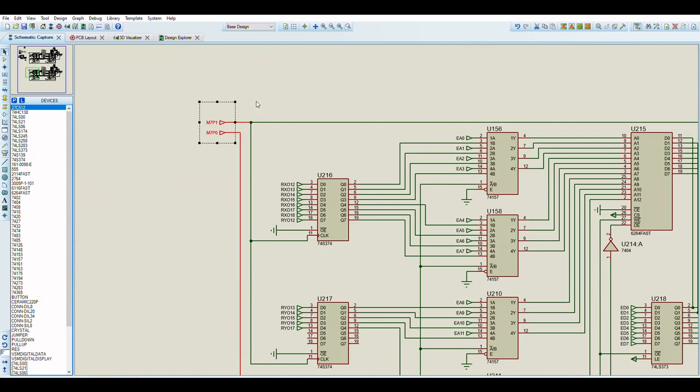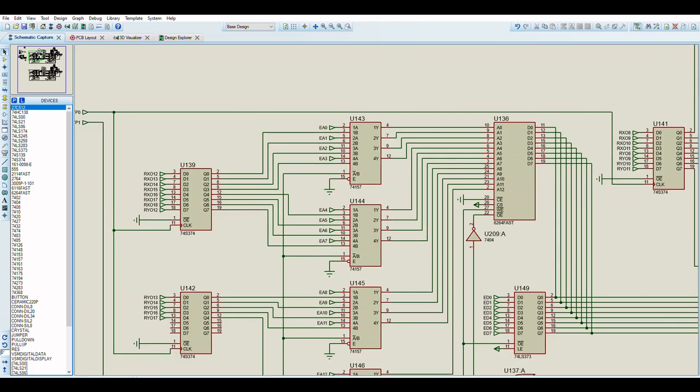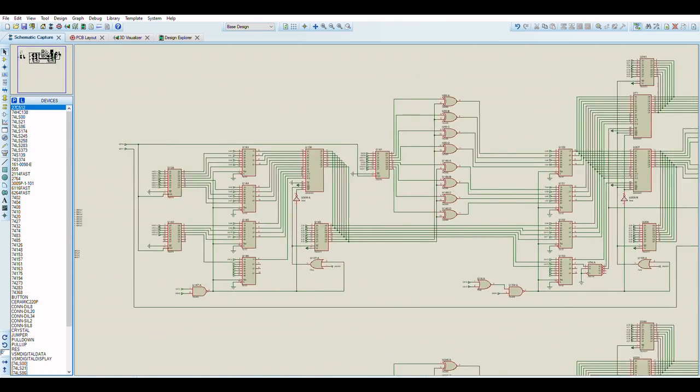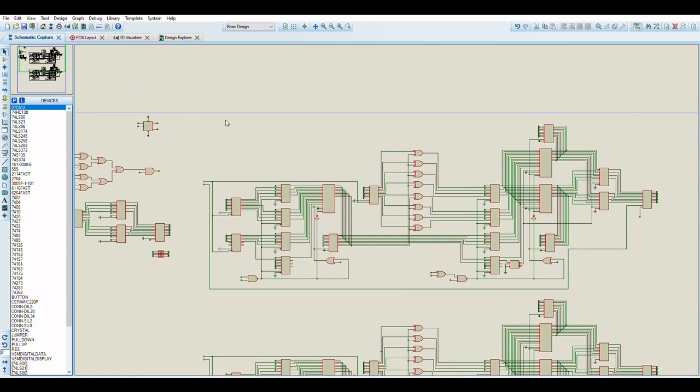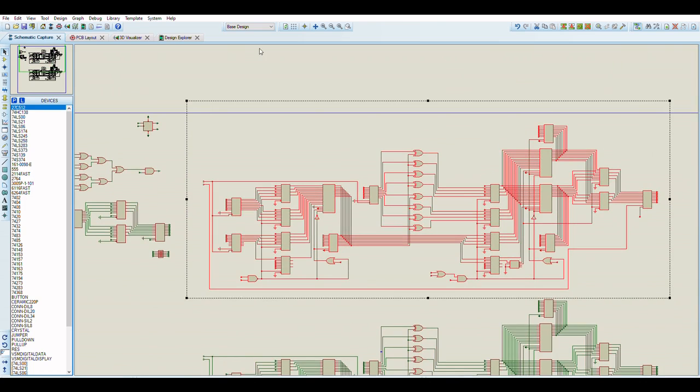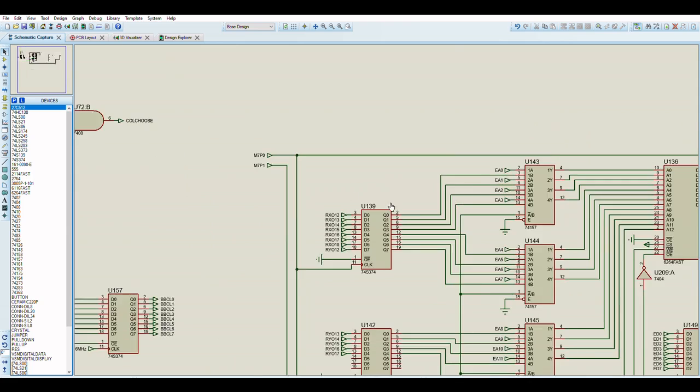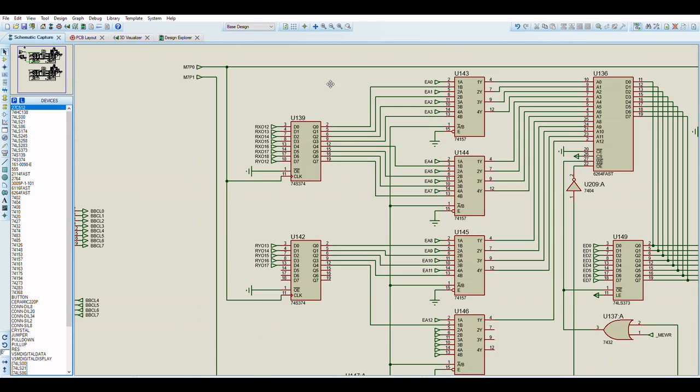So what this means is that while the first pixel pipeline is latching the upper bits, it discards the lower bits because they're just used for accuracy for the calculations. Fixed point integer maths.